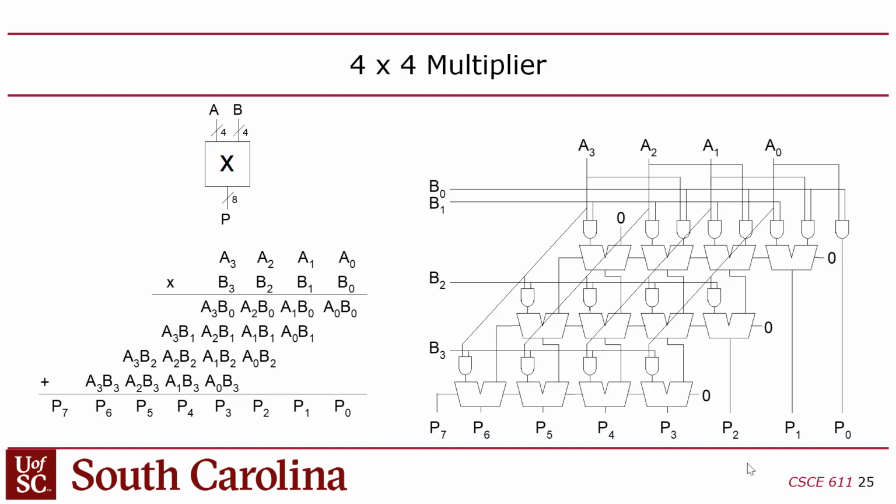You notice there are just 3 layers of adders here, whereas we have 4 rows here. And the reason for that is because if you look at this first row of full adders, this actually is taking care of these first two rows here, right? But then for every additional row here, you need 1 row of full adders, because you have to add the partial sum from the previous row.